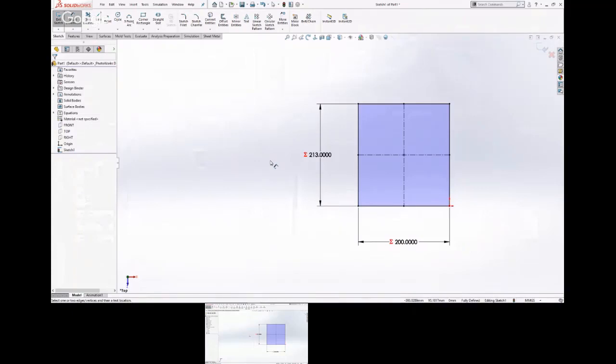But I think by default, it'll just carry across. If I make a configuration of this, they'll be there for that. So if I have the second configuration, I can go in there and change the equations and they won't affect the first. Yeah, I think it's going to ask you which configuration you want that change to apply to. And you can set all, or you can select the ones you want. Yeah, I think that's the beauty of configurations actually.